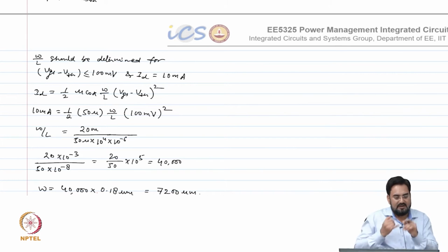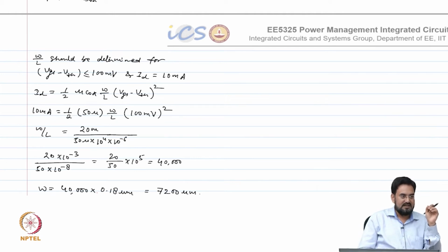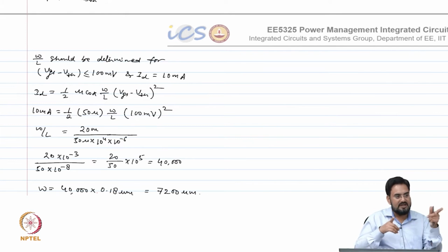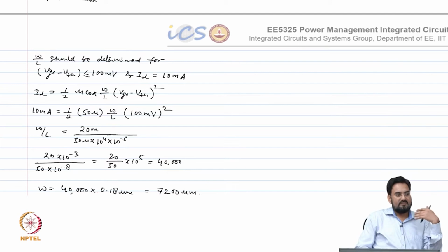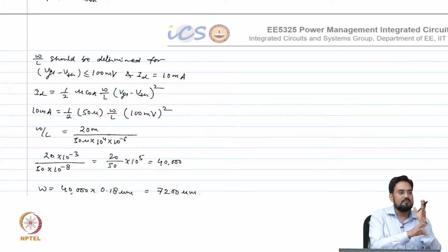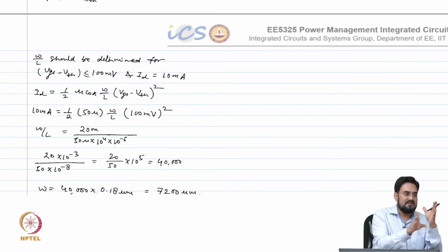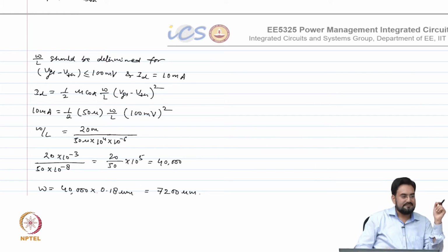So you cannot consider a fixed cap and fixed load and design for it, because it may become unstable. You have to always consider the worst case, and the worst case is defined by when both poles, omega P2 and omega P3, fall within your UGB. And mostly, when they are within UGB, the worst case will be when both are very close to each other.